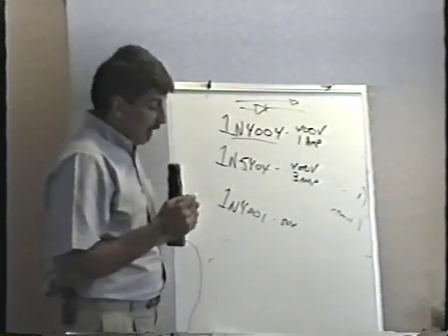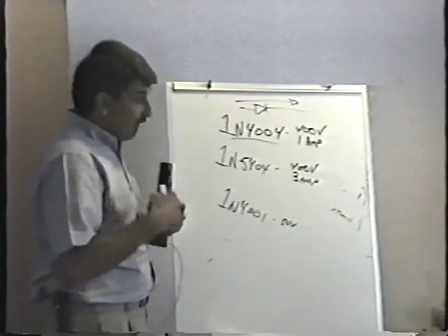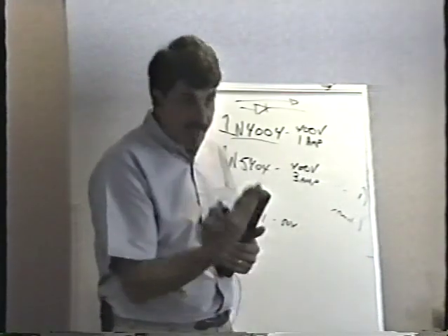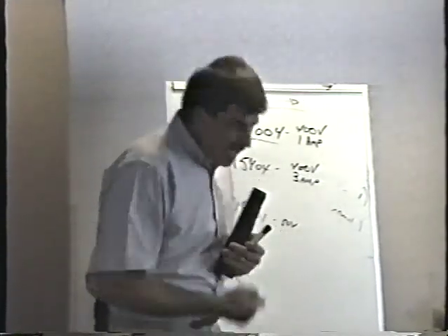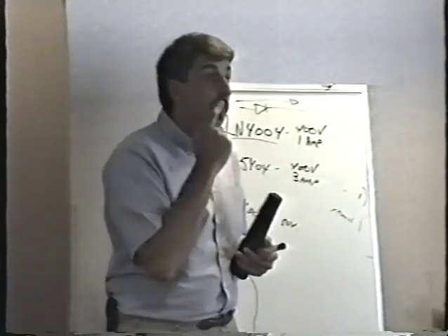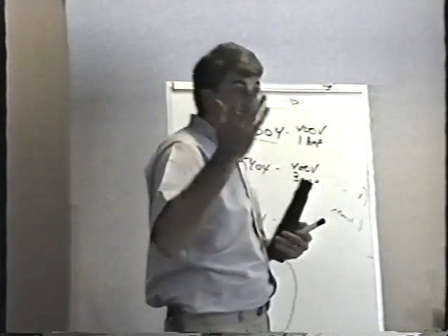What I'm saying to you is, you get to a location, you find a bad diode because it's shorted. You look at the number, it's a 1N4001. Shoot, all I've got is 1N4004s, and I have to go to Radio Shack. Well, you don't. You can use the 4004. You can go as high as you want.